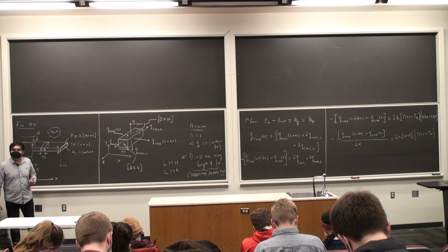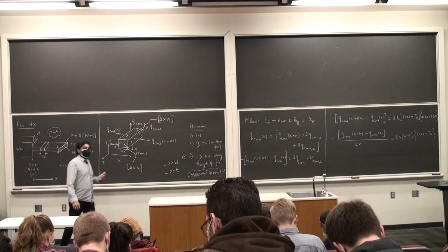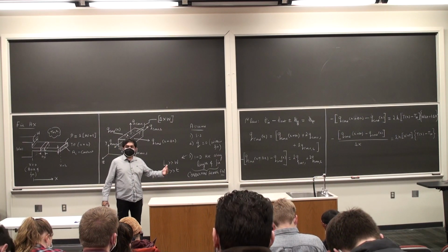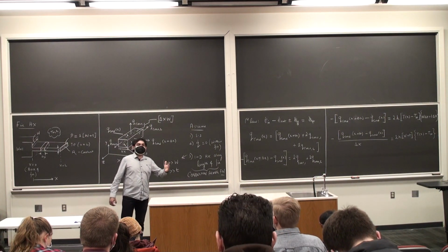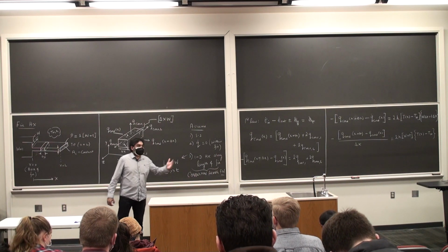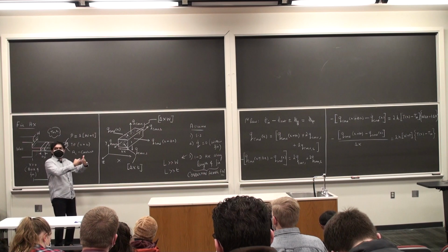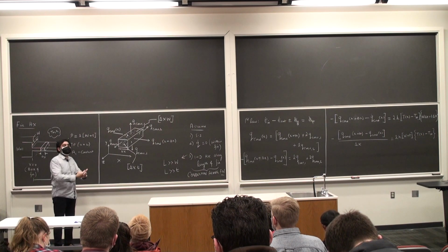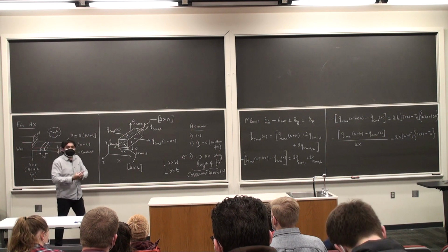There is a hidden assumption here. I am writing the convective heat transfer as T of x minus T infinity. That is also not the case. It has to be an average temperature along the x direction minus the ambient temperature. But I am assuming that this delta x is such a small element that in the limit of delta x tending to 0, the convective heat transfer can be given as T of x minus T infinity. That's another approximation that we're making.